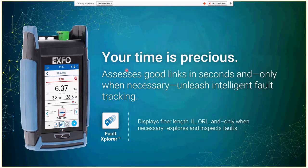So with the OX1, you don't need an OTDR to find the fault. You can find the fault yourself after measuring the power with the OX1. The way it's going to tell you is by pointing out that at 5.8 kilometers you have something, which is a connector in this case, a faulty one, which needs to be repaired. So it's not going to look into the whole link, it's just going to identify the element which is causing your problem, which is causing the fail or a lower rating on the Flash Advisor.